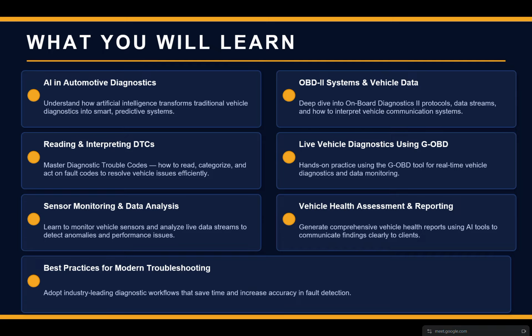But if I see another fault code on the braking system, I would know that that fault code is not related to the reason why my car is not accelerating as it should. So the fault code you see determines what you are going to look for. It's more like a guide to tell you, okay, this is the place you are going to check.